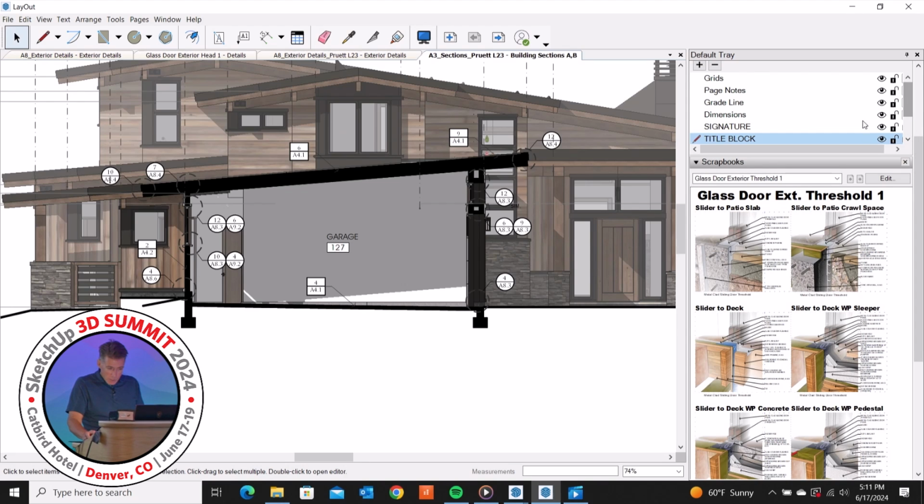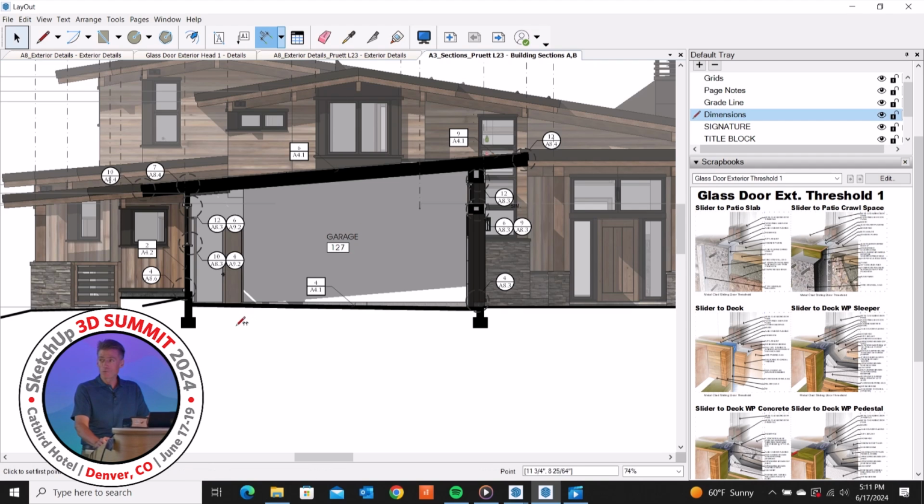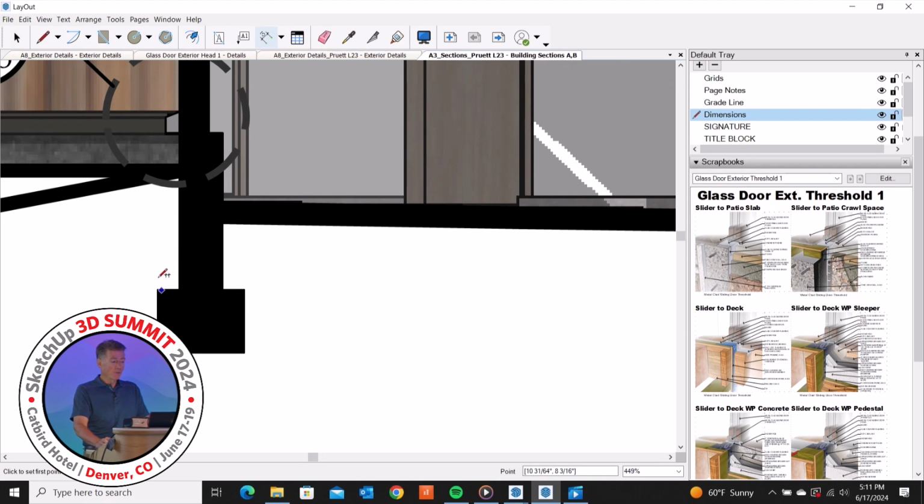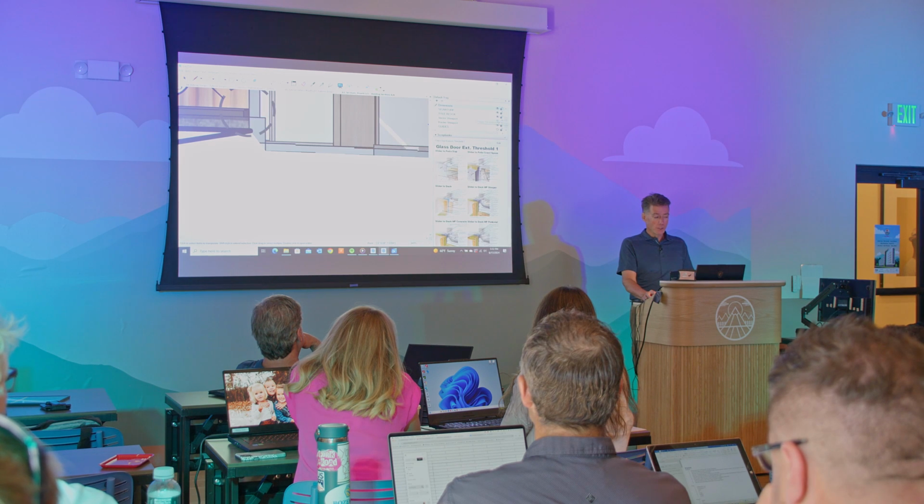Bear with me a second. Say I was going to do some dimensions on this, and I've got this hybrid layer on. I can't grab points. I can't even grab points. Well, sometimes I can. There it's capturing the edge. But sometimes it's difficult, especially on the floor plan, to grab anything. But there's no point to grab it. So when I dimension, I actually just shut that off. I have that on as a separate layer. So it's still labeled as vector viewport, because I used to do it all by generating from group from slice. I just shut that off.